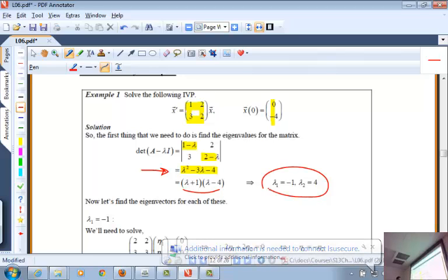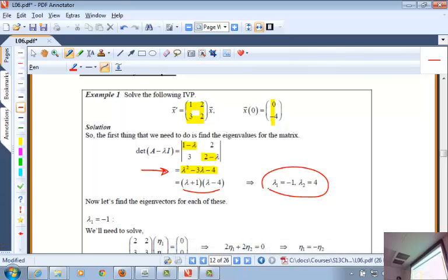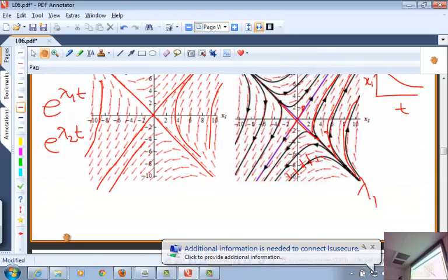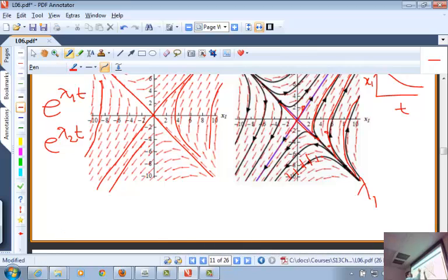So immediately you can conclude that the system is unstable because you have a positive eigenvalue. Even if you have 100 equations or 1,000 equations, if there is one eigenvalue that is positive, your entire system is unstable. Okay? So going back to the previous curve, you can argue, and this is the thing that we talked about, if I choose my initial condition to be exactly on this eigenvector, what would happen then? That initial condition does not have a component in the second eigenvector direction. What should happen then?